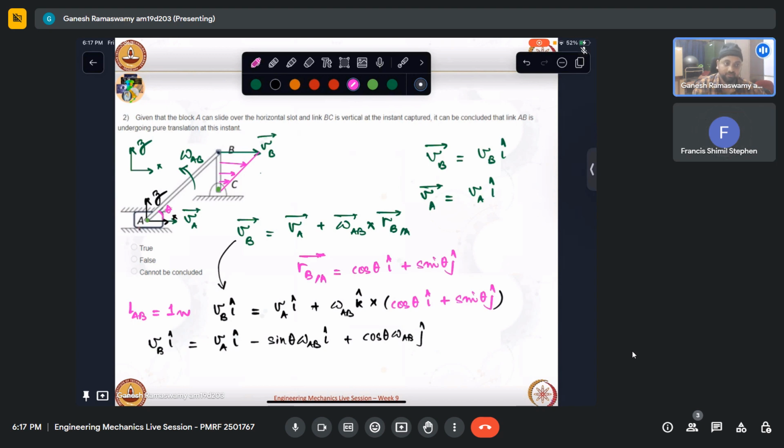VB, exactly. We need to find out only velocity VB. Then we need to resolve it along this direction. But mind you, we resolved along this and then found that this angle is also theta by virtue of knowing that both the velocities were parallel. If you know that both the velocities are parallel, then definitely only VB you need to find. VA automatically takes care of itself.